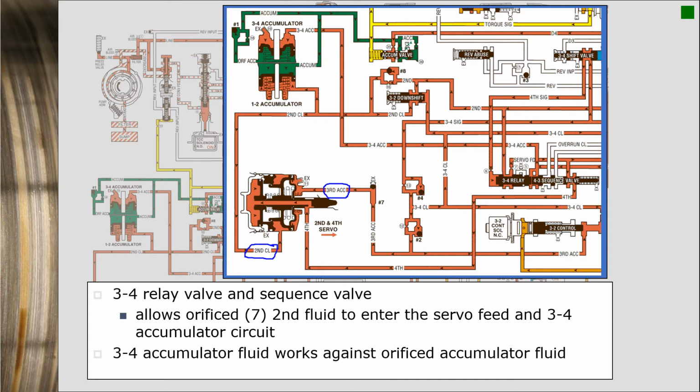Since we don't exhaust that, fourth pressure came in on its own little path, found its way through the pin, and worked on this fourth piston, which is completely separate from the other components, and was able to move the pin. Not the whole assembly, which still stayed shifted away from the case. Now we're moving just the piston, the fourth piston, and the pin, and applying it. It's kind of a neat little servo assembly that they've got.